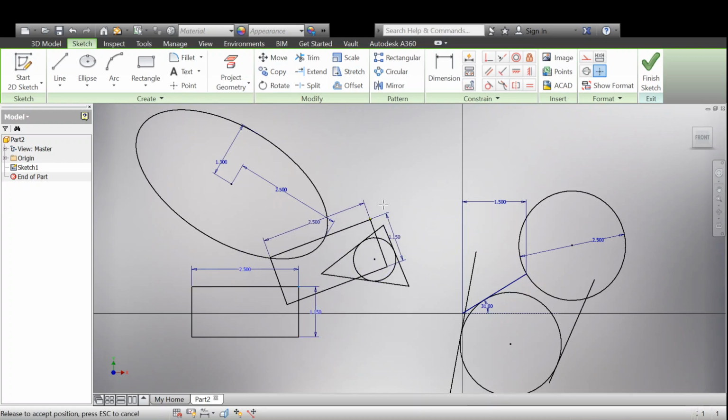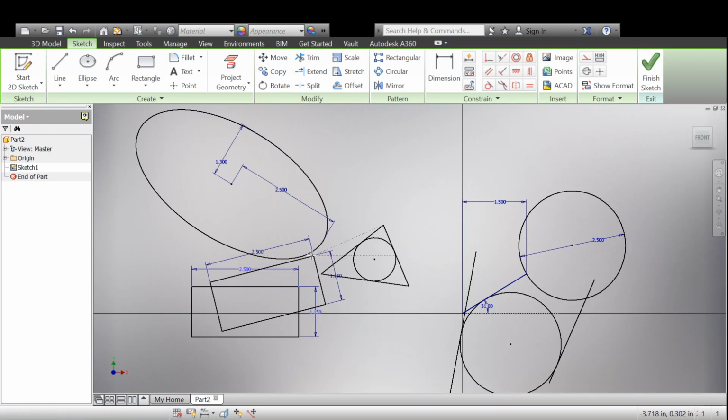See if I can grab the corner to move it. This is interesting. Very interesting. If I start moving one corner, it's changing the angle. Still, every time I try to delete one of those constraints, it deletes the whole line. So the first time you click on the constraint, the line is probably highlighted also. So click on it once more. Single click on that constraint one more time. When you right click on a constraint, it shouldn't show the whole menu, Chris. If I click on the constraint properly, and I see the whole thing appear, it's wrong. Click on the constraint again.